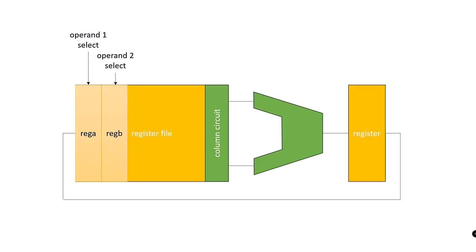SRAM is used to build register files in data paths. The SRAM structure provides fast register access times, critical for fast data path clock speeds. SRAM also supports multiple parallel accesses thanks to multi-ported RAMs. The row logic is controlled by the register file select signals. A register file uses several bit lines, one for each parallel port.